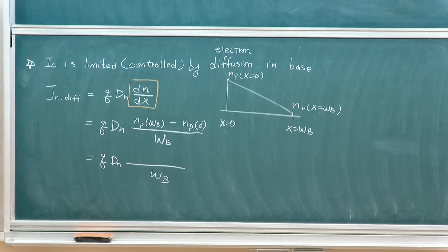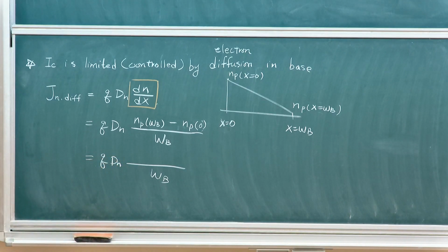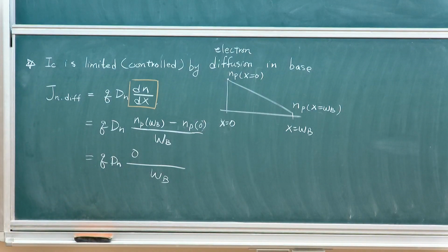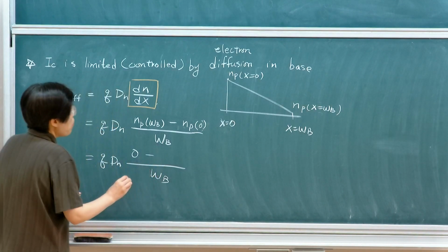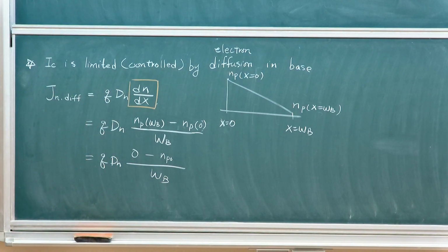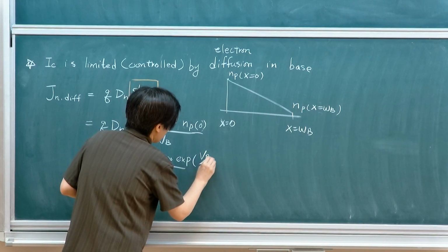Reverse bias p-n junction will pull it down, so it will be close to what? Give me a number. Just give a number. 0, correct. Just be brave. It's 0, close to 0, because it's already very low, and then we'll pull it down further. And the other side is forward bias, therefore, remember the forward bias equation, law of the junction, tells us that it should start with NP0 and rise by exponential VBE.